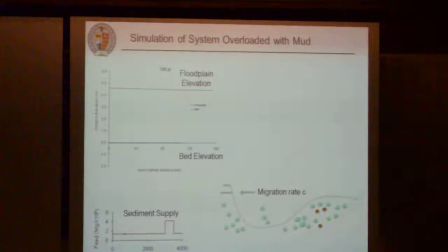You're bringing material out of the floodplain. We overloaded the system with mud, which meant, based on our partition model, that we had to put mud in the bar, which means we couldn't put all of the sand back in the bar. Okay, so we started from a case of equilibrium where the amount of sand eroding from the lower parts of the cut banks was being replaced in nearby bars.